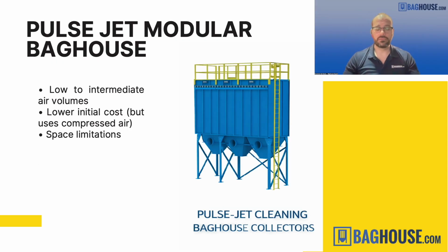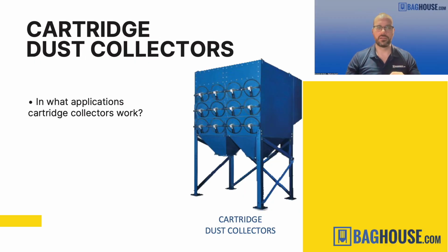Now, the most common type of dust collector for woodworking is a pulse jet style baghouse. Just like the previous collector, it uses filter bags. But instead of cleaning with a medium or low pressure back pulse of air, it shoots high pressure compressed air back into the filters to clean them off. This is kind of the gold standard for dust collectors, and it's used across all different kinds of industries and applications, not just woodworking. So a normal baghouse with pulse jet cleaning is the standard.